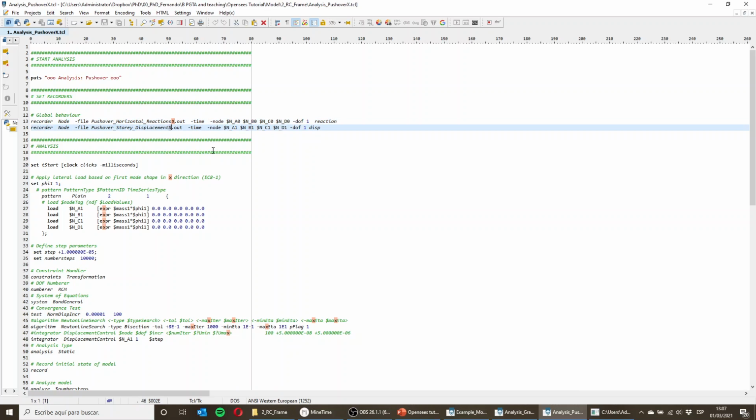displacement in X. Then after that, for the proportional loads, I am leaving everything very similar to the other steel moment resisting frame. I'm using the mass multiplied by the phi. In this case, it doesn't really matter because I have only one story. So my phi, the eigenvector at the end, is going to be 1. The value that corresponds to the story in the eigenvector for the first mode is going to be 1 because there's only one story. So I'm using this 1.